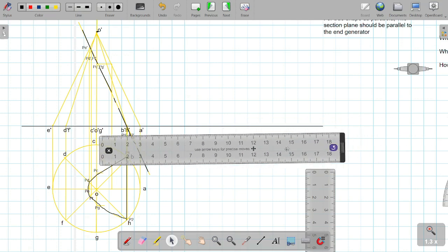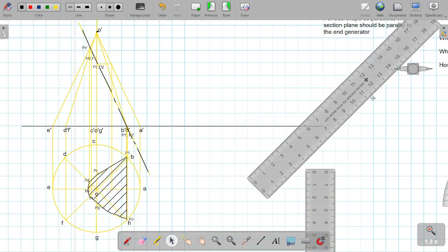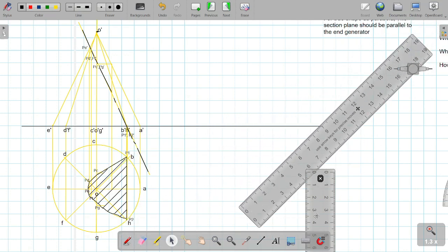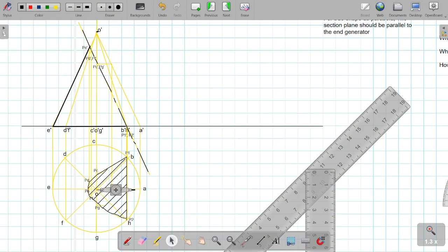Now I will draw the section in this. So now we will complete the remaining part, that is whatever is remaining we have to darken it. So this part is remaining, and in the cone only the outer will be made dark. So this point and this point is remaining, so this will be dark. Then in the top view I will darken this circle, the remaining part.